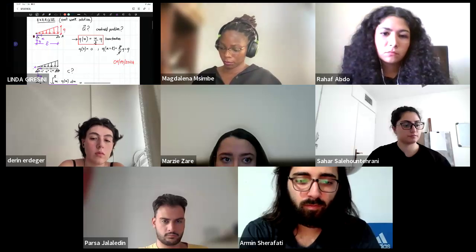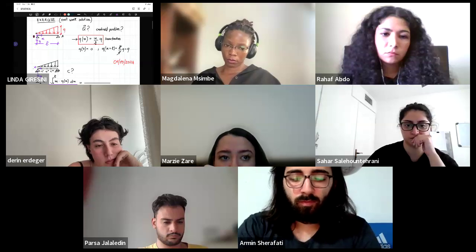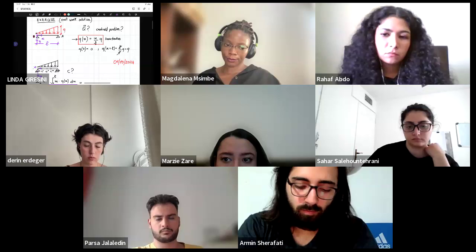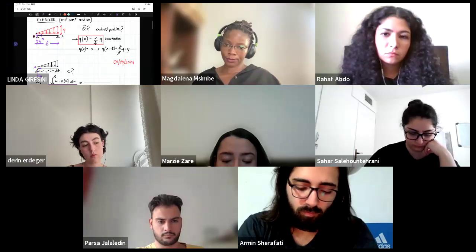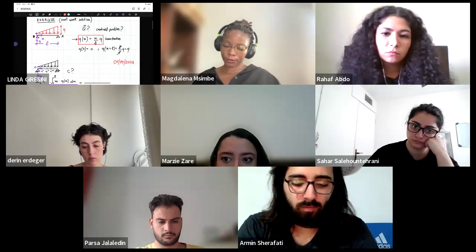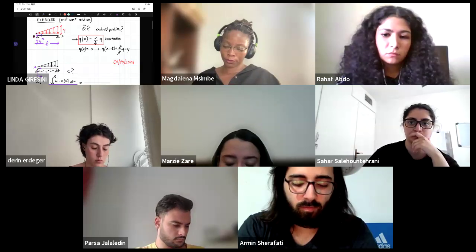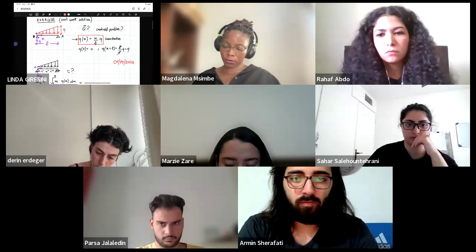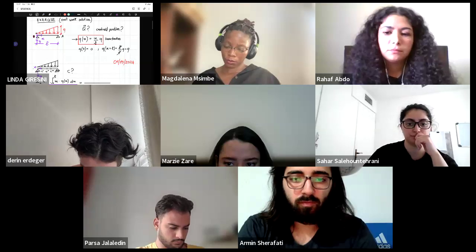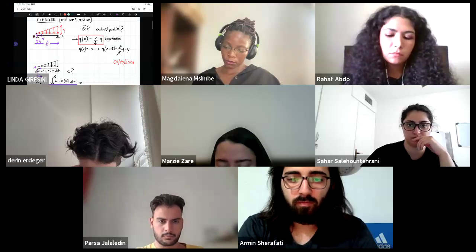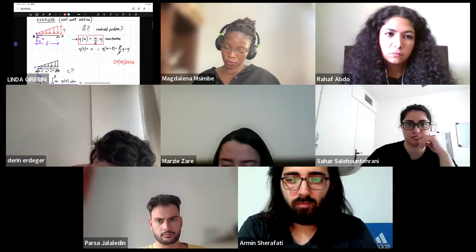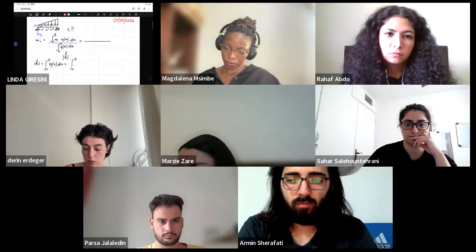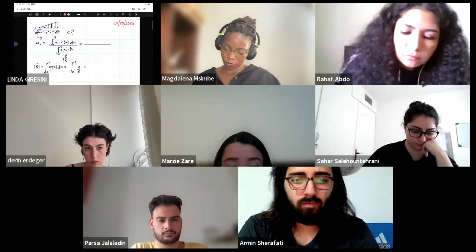Similarly, the concentrated force, what unit does a concentrated force have? Yes, newtons or kilonewtons, whatever, decanewtons, okay? And what about a volume force? What is the unit of a volume force? Kilonewton divided by cubic meters. Exactly. Because a volume is measured in cubic meters. So the types of forces are very important in structural design, so it's better that you have this concept very clear. Thank you also, Marzi, it's correct.